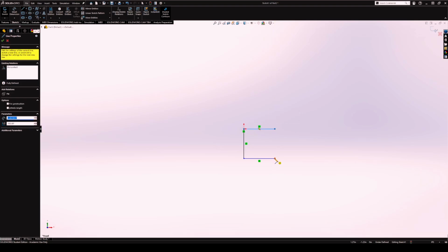Oops, it looks like I missed one. Let's finish that off. Okay, so after you've created a box and all of the lines are connecting, you'll see a shadow, and this shadow just means that, hey, you closed the shape, it's closed, and now you have a box that you can extrude.